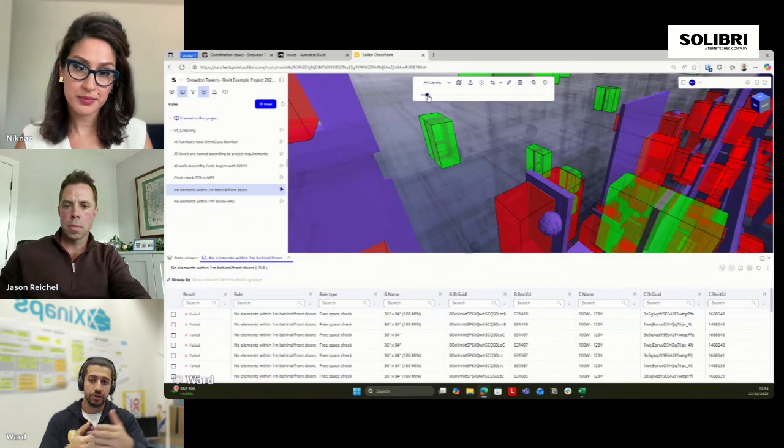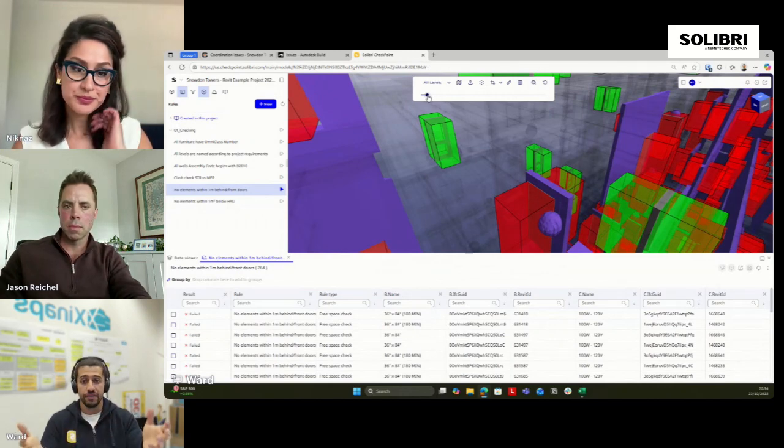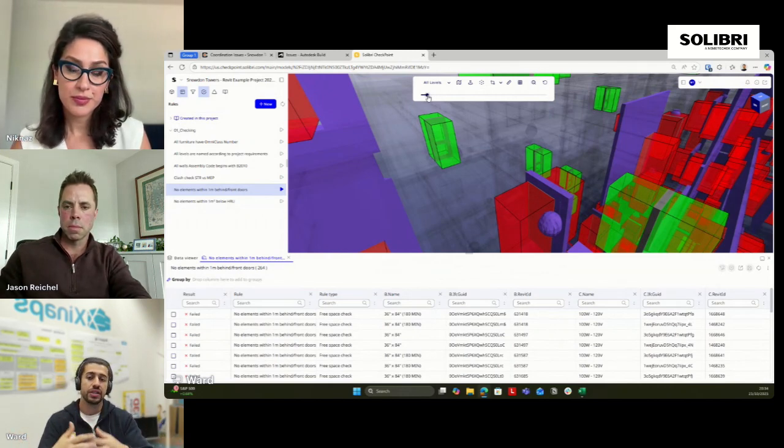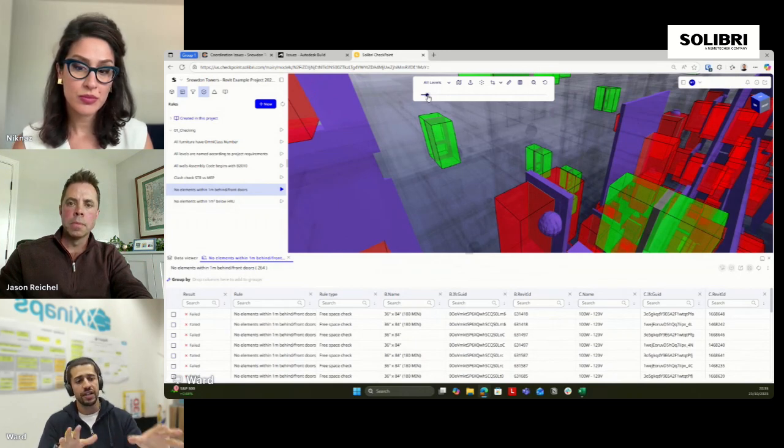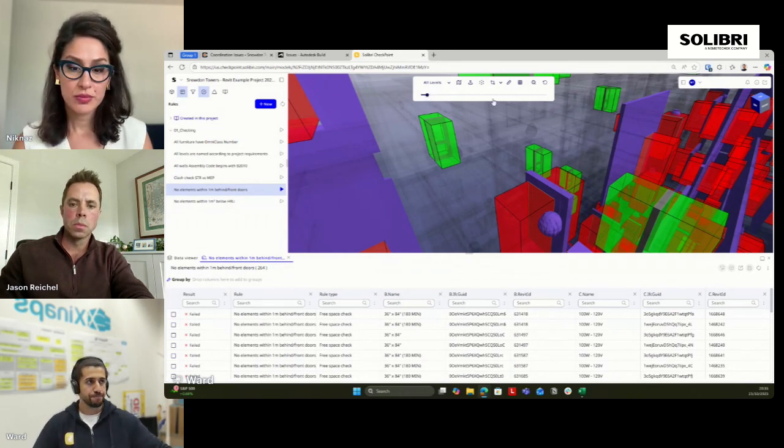You can add a geometry for the element. You can have them as generic models as well, but they will result in a lot of false positives, especially when you run a clash check, you export into another platform and then run your clash check on the other platform. Of course, it will result in a lot of false positives. And that's why the data viewer, along with the free space check, is a good combination for the soft clashes.